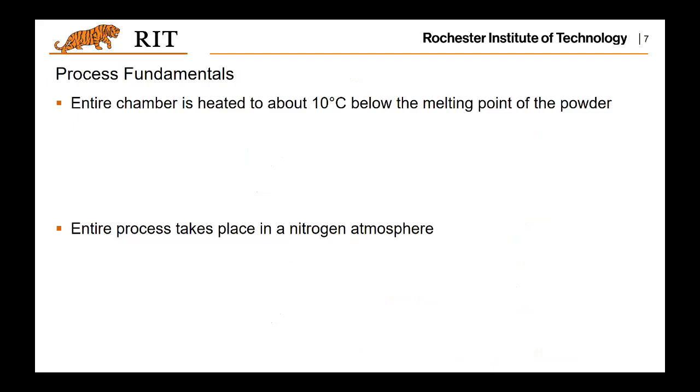So the whole chamber is at a high temperature, and that will increase the laser scan speed. Because if you do not heat up the entire chamber, then you probably need a very powerful laser, or you really slow down the laser scan, right?